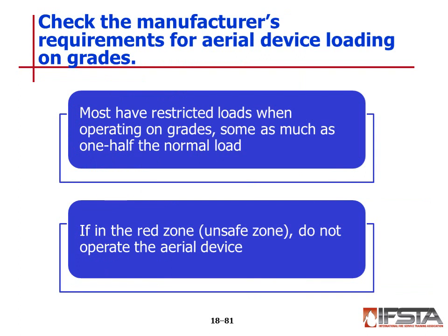Always make sure to check manufacturer's recommendations for aerial device loading on grades. Most have restricted loads when operating on grades, some as much as half of the normal load. If in the red zone or the unsafe load, do not operate the aerial device.